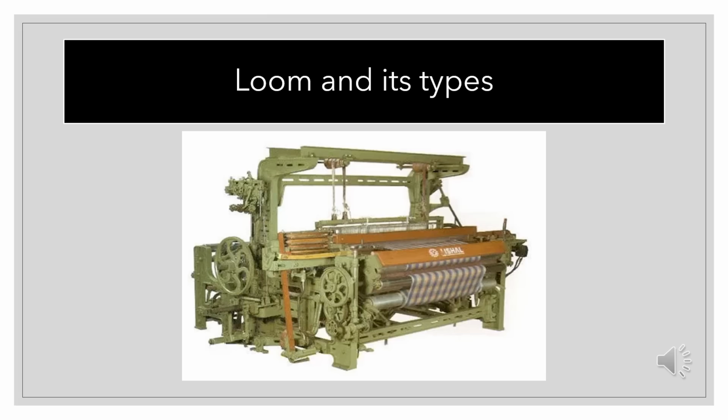Water jet loom. In the water jet loom, a water jet is propelled across the shed with the force that takes the filling yarn to the other side. In it, a pre-measured length of weft yarn is carried across the loom by a jet of water. These looms are very fast, with speeds up to 600 ppm, and very low noise. Air jet loom. In the air jet loom, a jet of air is projected across the shed with the force that takes the filling yarn to the other side, i.e. a jet of air is used to propel the weft yarn through the shed at speeds of up to 600 ppm. Uniform weft yarns are needed to make fabrics on this loom.